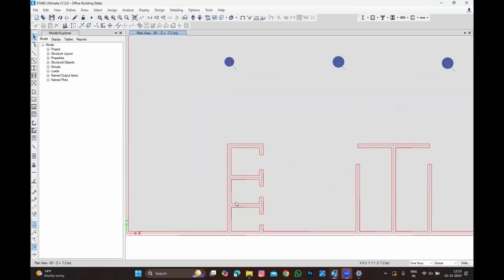In the lift there is an opening, right? Yeah, in the lift actually. So we'll model the opening here. Same option, same option, same option. But in the property, instead of slab property, I will choose the opening. Okay, if you scroll down, you will find the opening.